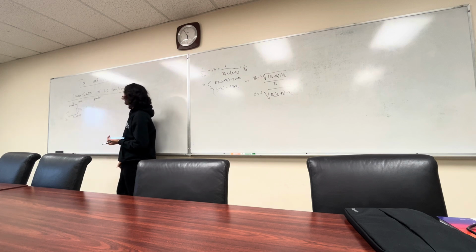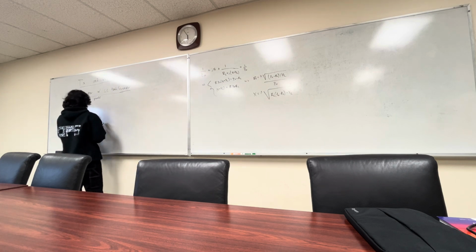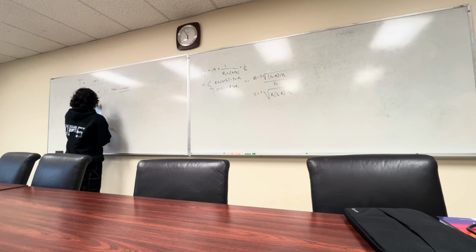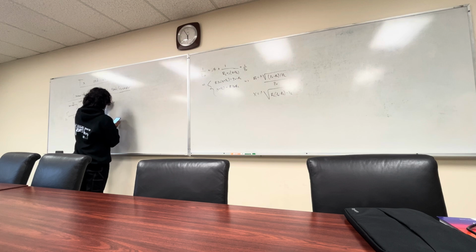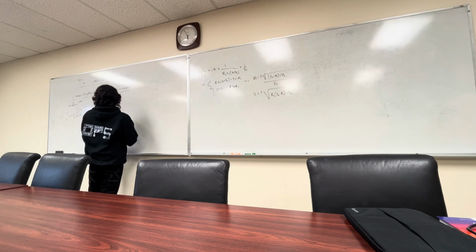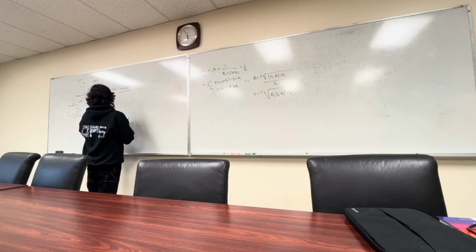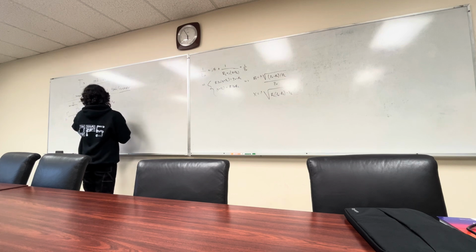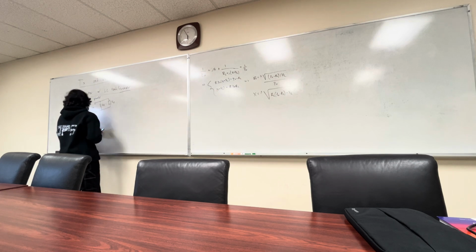Kind of the same idea here, right? How do we go from series to parallel? Ideally, RS transforms into some resistance, call it RP, and this XS also transforms to some reactance, call that XP. Now if we just do a bunch of KCL, KVL, we can hopefully get a meaningful relationship between how these values correspond to these ones, such that this ZS is the same.